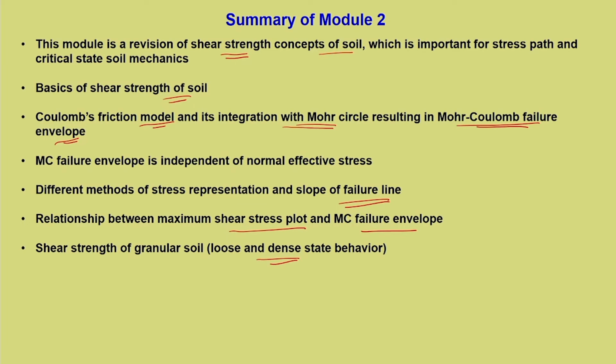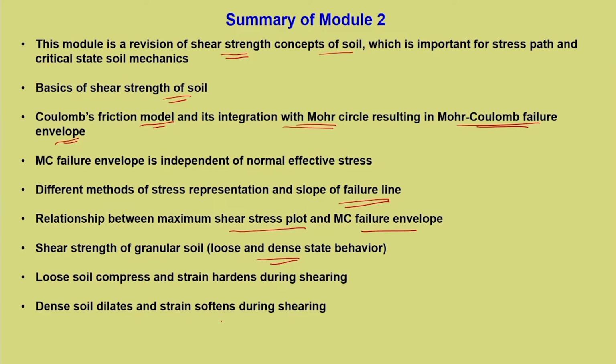Shear strength of granular soil, we have discussed in detail how the loose and dense state of the soil influences the shear strength. Loose soil compresses and strain hardens during shearing, dense soil dilates and strain softens during shearing. So these aspects we have seen in this lecture.